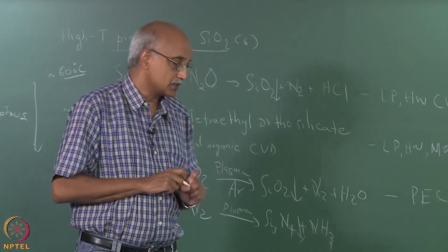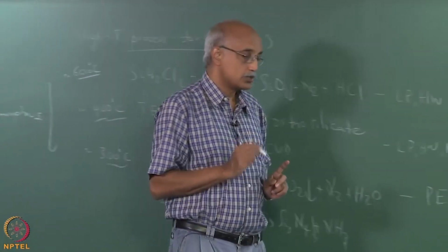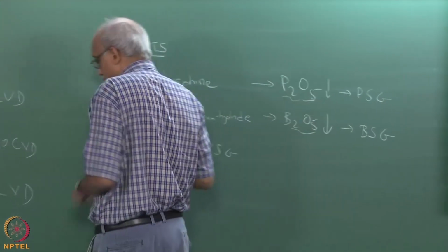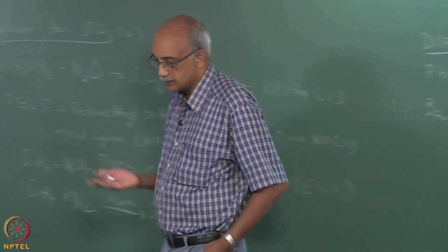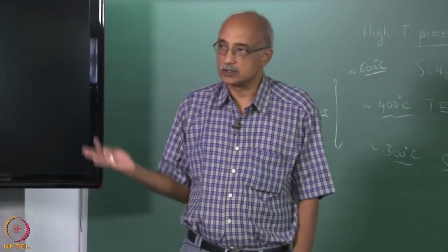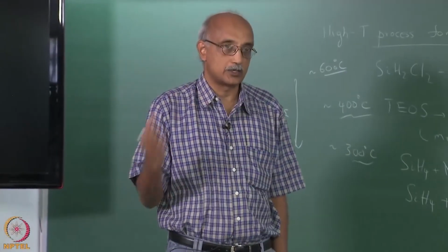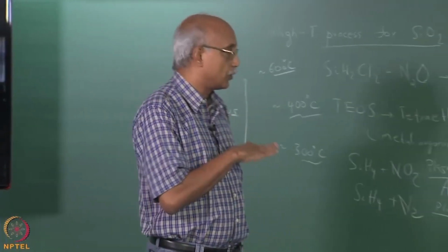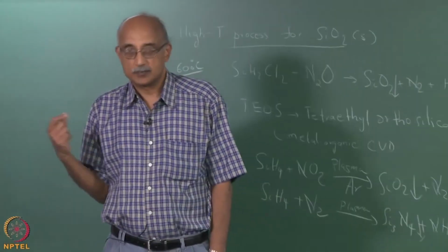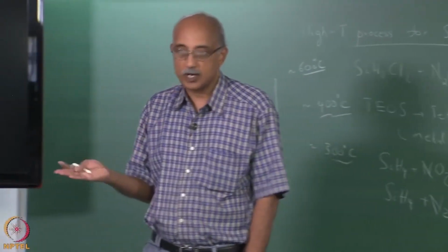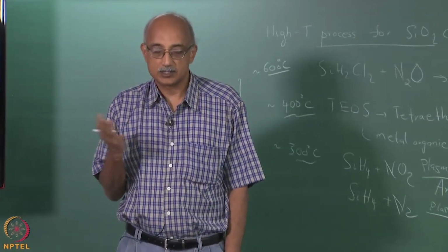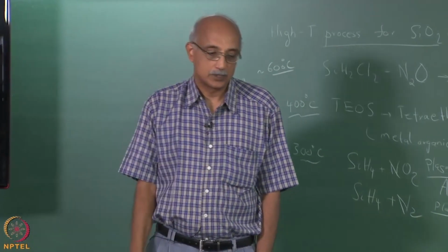And again, the point here is that when you are trying to use these dopants, and the idea is to incorporate certain materials into the oxide itself, there is no way you can do this if the glass has a crystalline structure to it. You can only do this if it has a polycrystalline or amorphous structure to it, and therefore, particularly in applications where you know that you are going to be using dopants, it is pretty much a requirement that you run under conditions where the surface is somewhat deformable, so to speak.